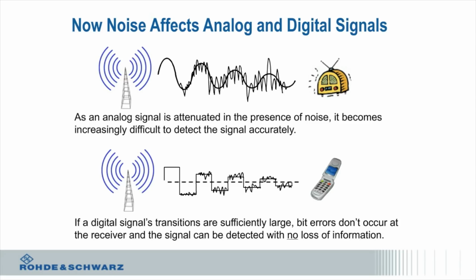As it's reduced in amplitude, it becomes more and more difficult to detect that signal relative to the noise around it. So you'll see an analog used to have that hissing noise, but digital receivers actually have coding put into the signal, so it has redundancy built in. So typically you won't have that hissing noise, but you'll have a more steep break-off where you will start having blocks of data where there's no sound at all, for example, on a satellite radio, or you'll just lose your signal altogether.